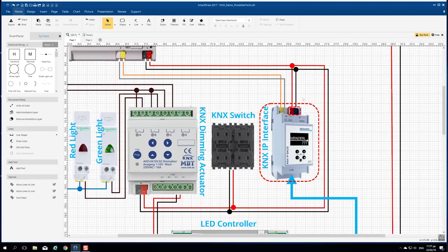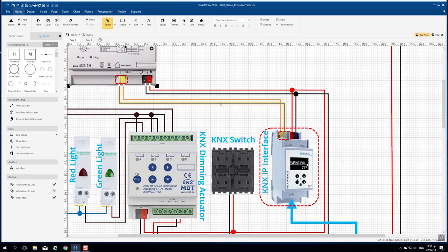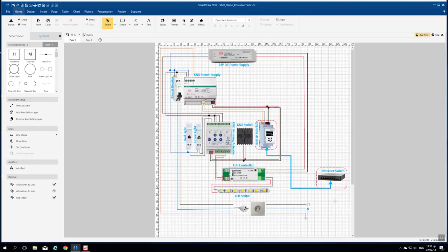The connections needed for this KNX IP interface are the red-black cable from the KNX bus and also an external DC power from minimum 12 to maximum 30 volts. We can take 30 volts from the secondary port of our KNX power supply. We can avoid the external power by using a PoE switch. Now that we have finished with all these connections, let's see the real project.